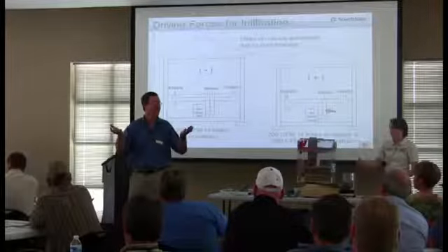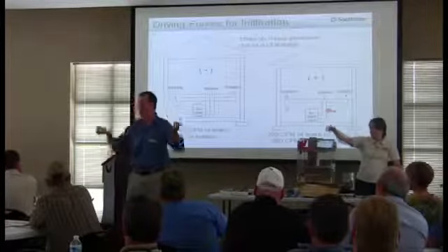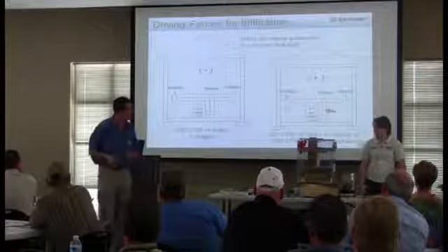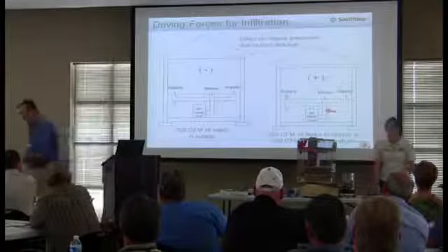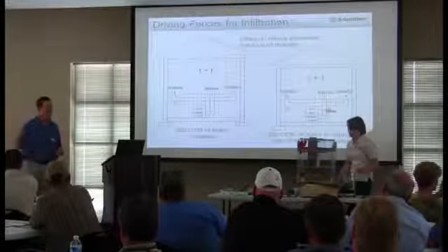What's the other thing it might tell you? That you have the same amount of supply and return leakage, which is what I'm trying to show you on this one right here. We got the same amount of duct leakage on the supply side and the return side. That's not how you fix the problem, by making equal size holes, just in case you're wondering.